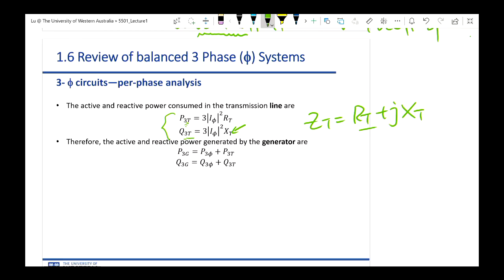Yes. Can this resistor consume reactive power Q? No. A resistor can consume real power only, or you call that active power, same thing, okay? A resistor can consume active power only. Reactance cannot touch the real power. The reactance X can consume reactive power only.